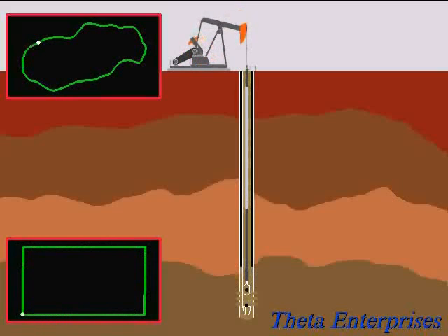Well, it's all relative. This is relative to the surface speed, of course. So depending on the pumping speed, I'm sure there's some correlation. I haven't done any studies myself to show that, but it would only make sense that if the plunger is moving faster, there'll be more wear. Or maybe the other one, where that plunger was starting and stopping and starting and stopping. Yeah. You would think you'd like to have your traveling valve moving nice and easy, not a lot of starts and stops.